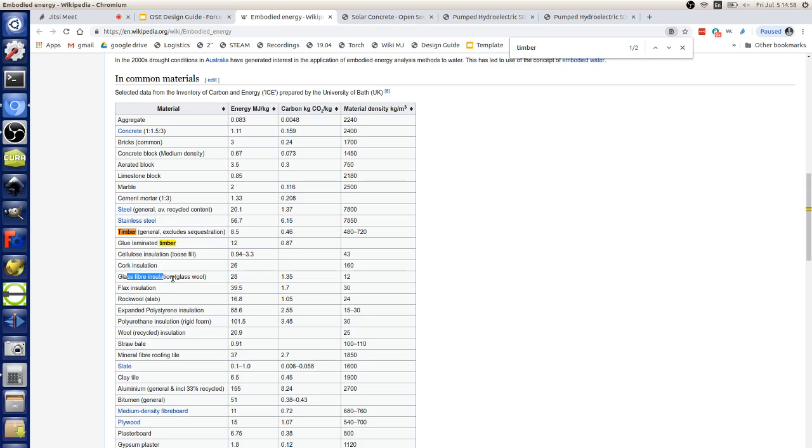That's quite a bit. How much is for marble? Marble? Talk about marble. It's so expensive. I want to know why. Marble is only 2. That's amazing. In terms of energy content, basically you're cutting marble from quarries, which takes about 2 times as much energy as actually burning rocks to get cement. It's 2 megajoules per kilogram versus concrete 1 megajoule per kilogram. But concrete, we're talking about the mix where it's cement with the aggregate.